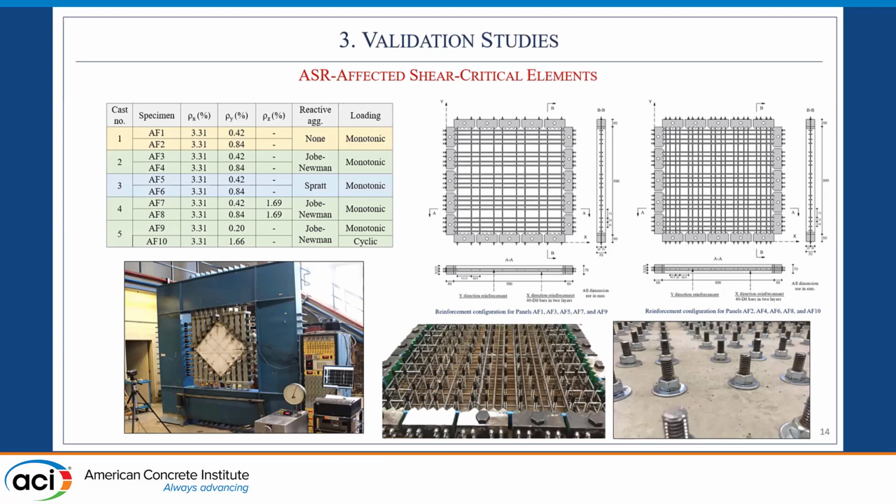And first, we're going to discuss the validation studies performed on shear critical panel elements. 10 panel elements were constructed and tested at the University of Toronto. We can see here the test setup. They were subjected to pure membrane shear. They were cast with varying amounts of in-plane and out-of-plane reinforcement.